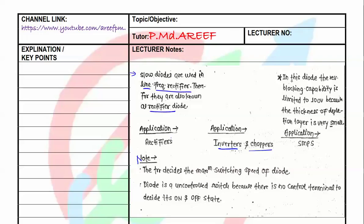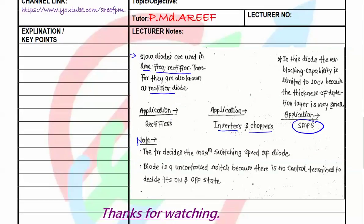And in Schottky diodes, the reverse blocking capability is limited to 100 volts because of the thickness of the depletion layer, so it's very small. These are used in switched mode power supplies. So the important notes here: the TRR, the reverse recovery time, decides the maximum switching speed of the device. The diode is an uncontrolled switch because there is no control terminal to control its on and off states.